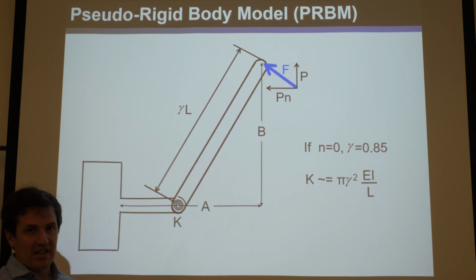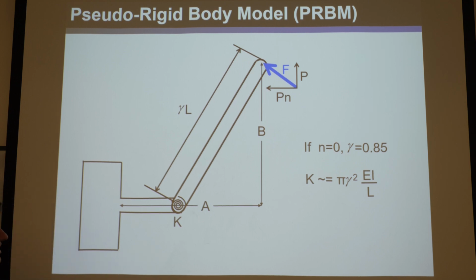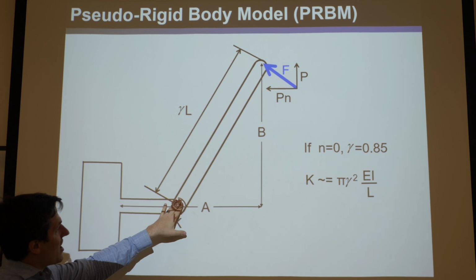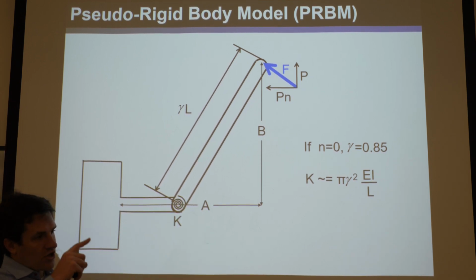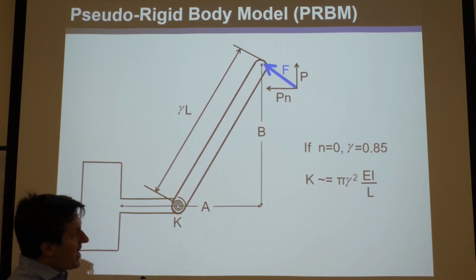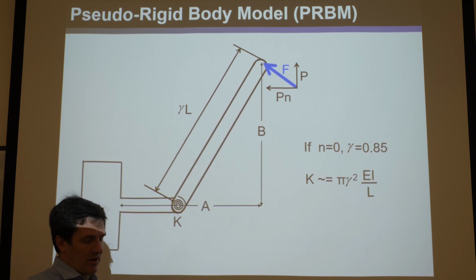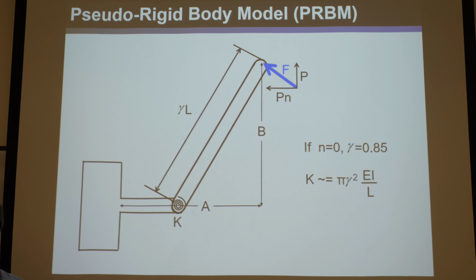But then how do you capture the elastomechanics, the stiffness of it? Well, he puts torsional joints there, and it says, this will approximately be the same kind of torsional stiffness as the beam would exhibit according to this equation, which, his derivations are in the textbook he wrote on compliant mechanisms, and a lot of that talks about pseudo-rigid body model and how he derived these things and how he came up with these models, okay?